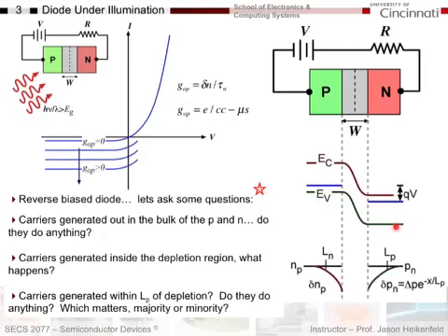It'll just get hot. Basically, light will come in, you'll generate electrons, it'll generate a hole, they'll move around, they'll find each other, and it will recombine, and that recombination will go back to heat. And so way out here in the N-type and the P-type regions, all I'm going to do is basically make this PN junction heat up, which is not generating electrical energy, which is what I'm after.